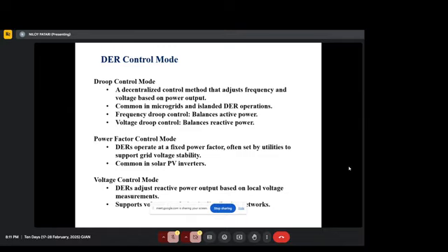In any feeder model, most of the time you'll find huge capacitors at the substation side. Its main function is to correct power factor. And then there are some capacitors at the periphery to improve the voltage. But I'm just giving an example.